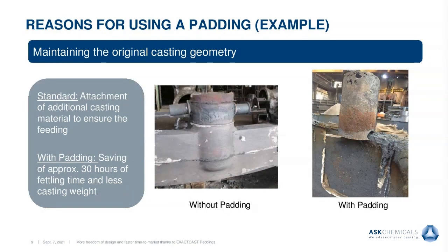So this is a very simple steel casting geometry. It's a ring-shaped geometry where you have, as you might know it, some bumps on the sides under the riser so that you can have the right feeding distance, that your feeders are working and your feeding solution is working. And what you can do here with the padding is you can just simulate in a thermal way these kind of bumps or this kind of extra material with this exothermic padding you put aside directly under the riser.